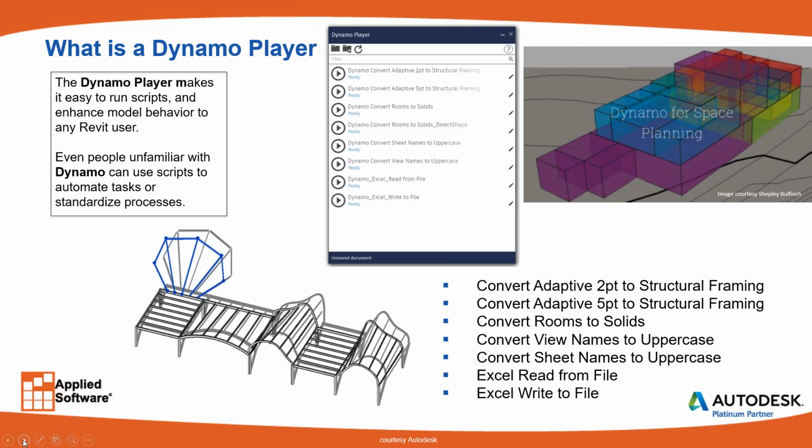So as I said before, the Dynamo Player is the interface that is meant for the end user. The end user doesn't see the programming part of it, neither the scripting nor the visual programming. They only see the player. All they have to do is look for which Dynamo graph they want to execute and press the play button, and there it goes. A good example would be to turn spaces and rooms into solids to study the massing inside of the project.